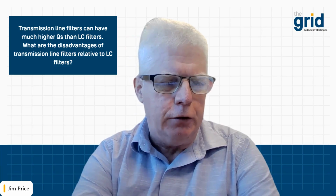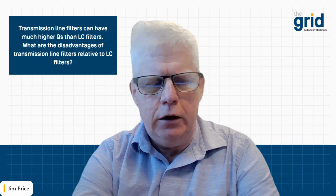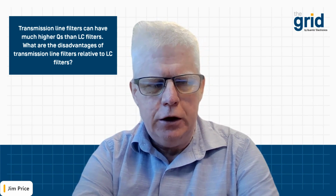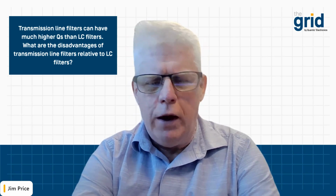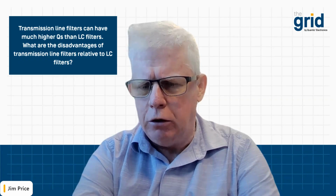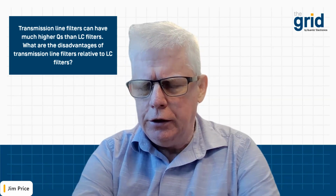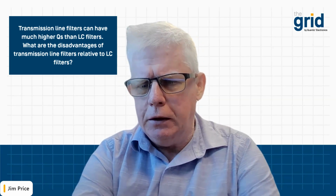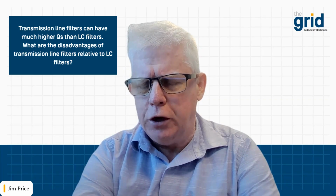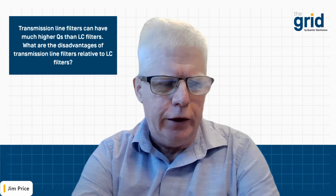Another disadvantage of transmission line filters is they can become quite large at lower frequencies, because they're wavelength based design. Lower frequencies are longer wavelengths, so the elements can get large. So if you're sub a few hundred megahertz, you generally want to stick with LC filters or something like that to avoid that problem, the size and weight problem.